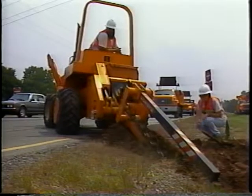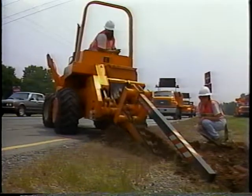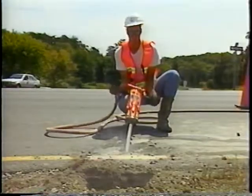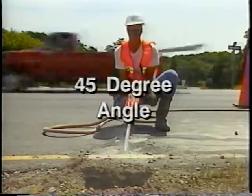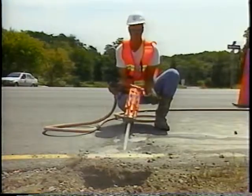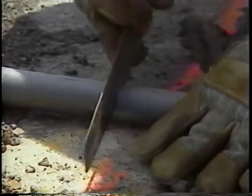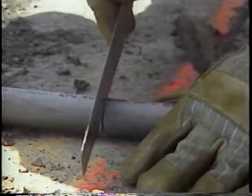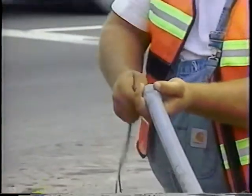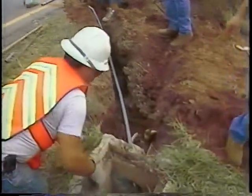At intersections with shoulders, as in our example, dig a trench from the pull box location to the pavement. Then, at a 45-degree angle, core drill a hole at least 6 inches from the edge of the pavement into the trench. Next, cut 1-inch, thick-walled PVC conduit to the correct length and place in the core hole. Run the wire through the conduit and then the conduit above the drainage line to the pull box.